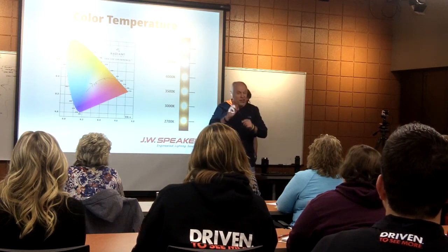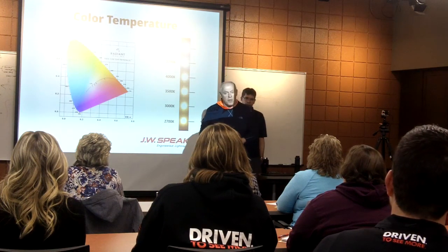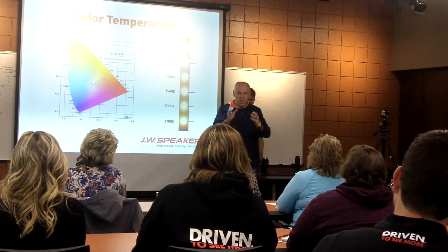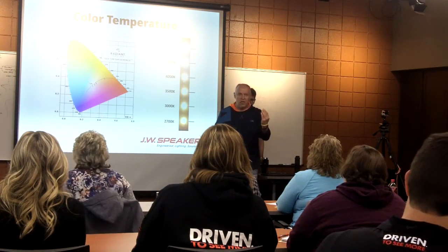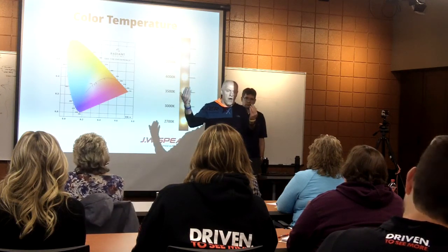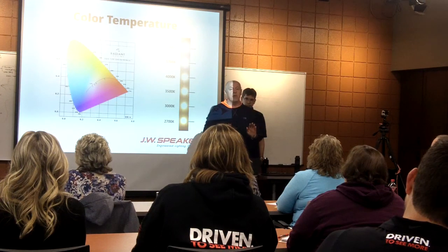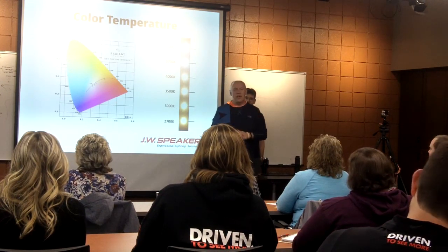That is a very tight tolerance, and it's a lot of money. So what we are working with is plus or minus 500 Kelvin. But if you take two lamps, one at the low tolerance of minus 500 Kelvin and one at the high tolerance of plus 500 Kelvin, you will see a difference in the color temperature. It doesn't happen that much, but you will see it.